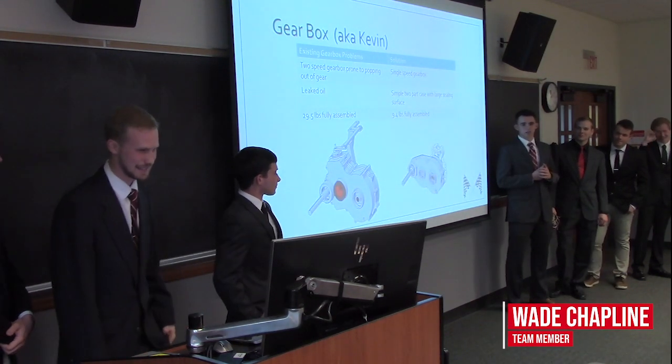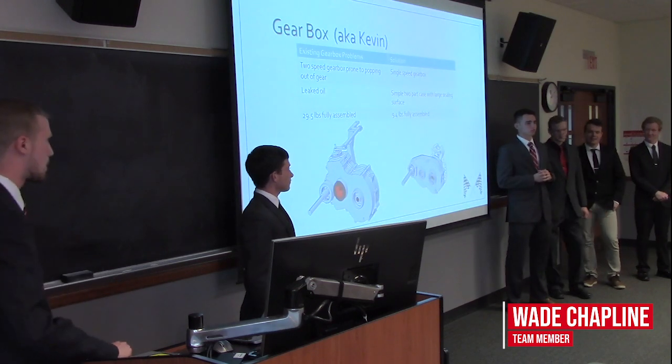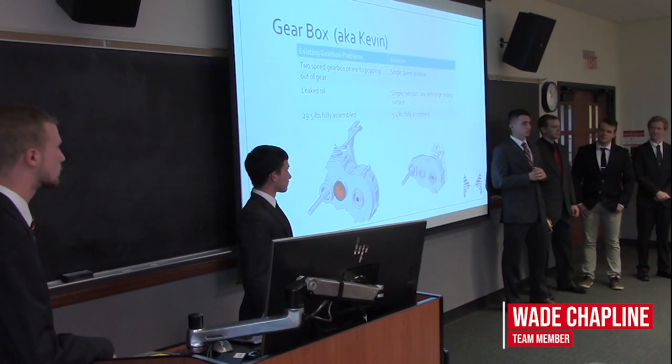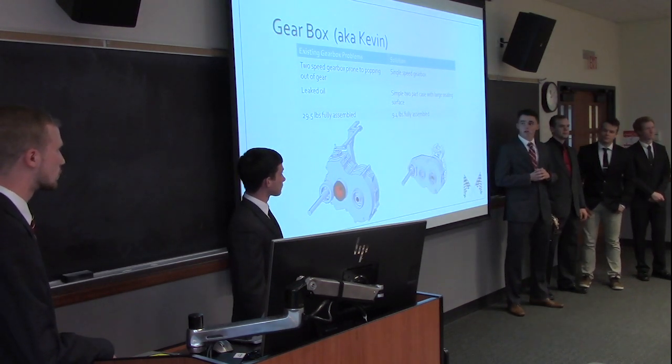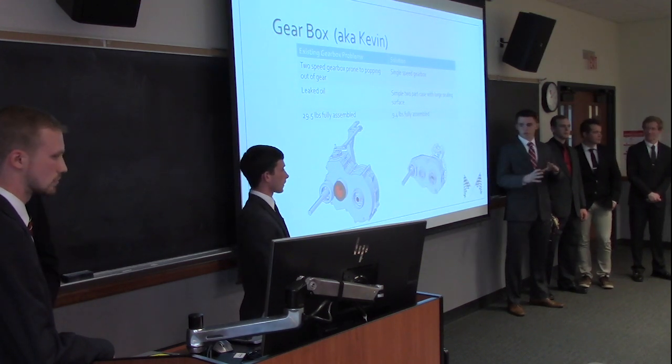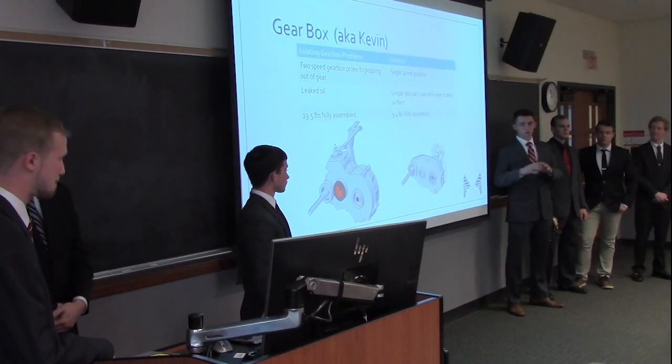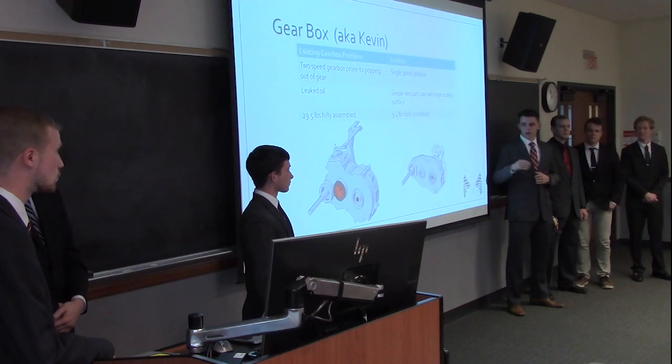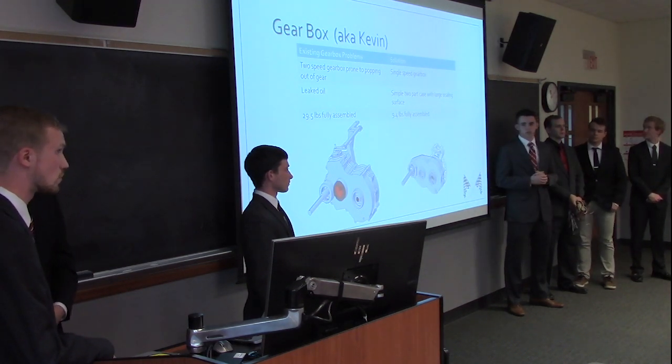Yeah, so as Jonathan mentioned, the second side of our project was to design and manufacture a new gearbox for the Baja car. The gearbox takes the output from the ECVT, reduces the speed to provide more torque, and then transmits power to the rear axle of the vehicle.